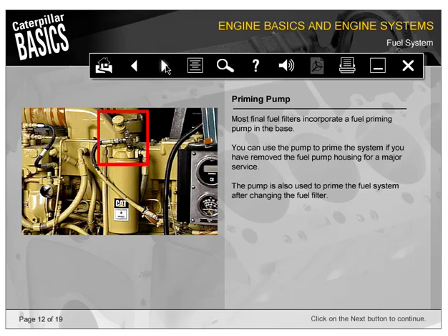Most final fuel filters incorporate a fuel priming pump in the base. You can use the pump to prime the system if you've removed the fuel pump housing for a major service. The pump is also used to prime the fuel system after changing the fuel filter.